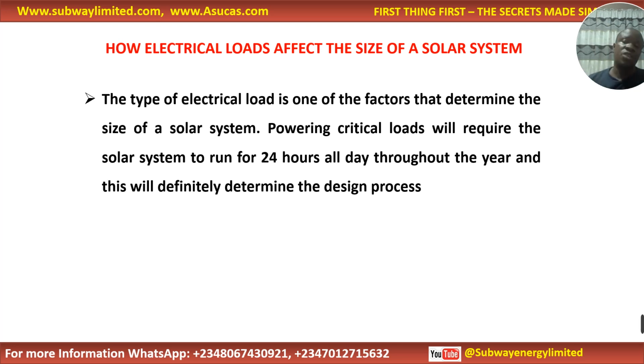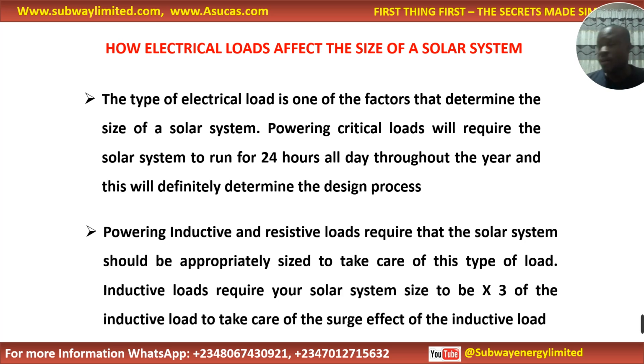This system will be running 24 hours. Do you know what that means? Even if it is a CCTV camera, you put in a good number of backup. Powering inductive and resistive loads requires that the solar system be appropriately sized to take care of this type of load. Inductive loads require your solar system to be sized three times the inductive load to take care of the surge effect of the inductive load.